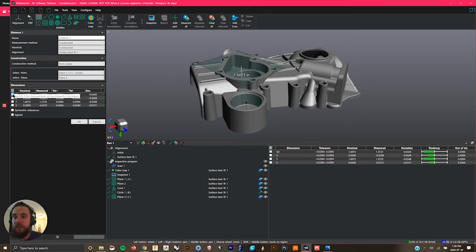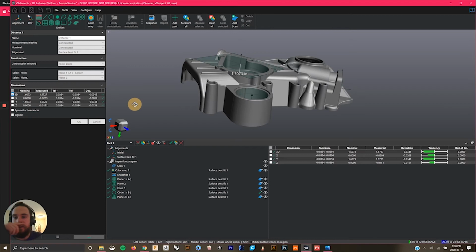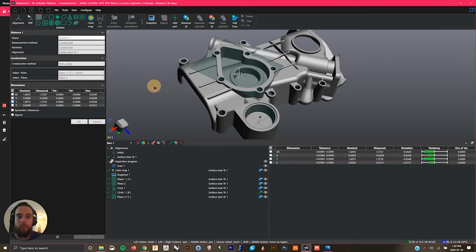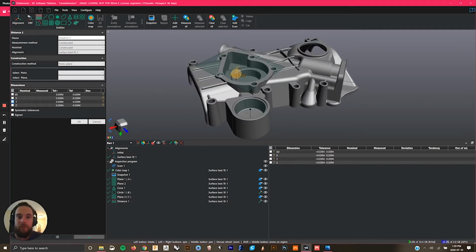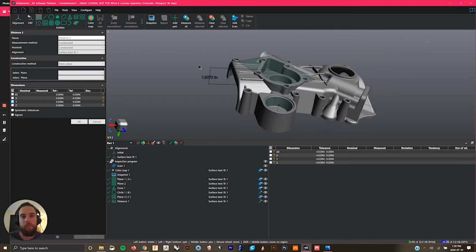And it has a 3D value that I can specify, and it's X, Y, and Z. What I want specifically is its Y. I don't want any 3D deviation at all. Thankfully, they're both the exact same measurement here, but it's better safe than sorry, especially if you get a weird part later on. We want to make sure that it's specified as just the Y that it's going to report out. And of course, we can change this later. But now we have that floating measurement here, which we can also drag off the part so we can see it better.